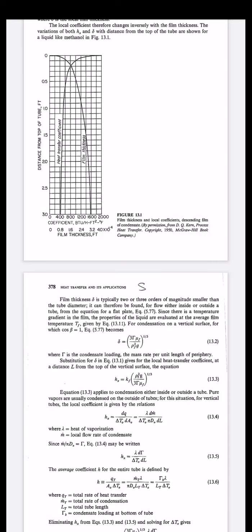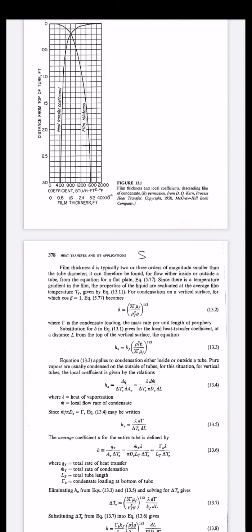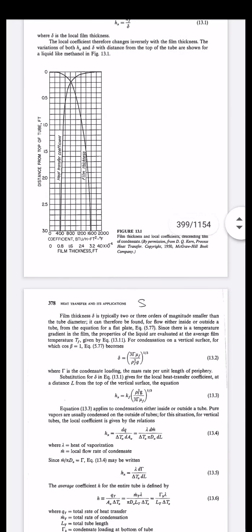Generally, a cold commodity is passed through the tube side, and the mixture of vapors is allowed to enter the shell side. So whenever a mixture of vapors reaches a temperature which is less than the condensation temperature, at that temperature the phase transfer takes place, that is, the vapors are going to condense on the outer wall of the tube, and thus heat of condensation, which we discussed earlier, and heat of vaporization are both important. Here heat of condensation is very important.